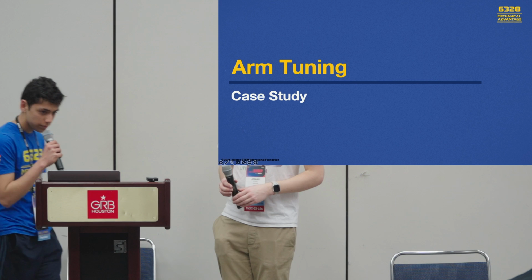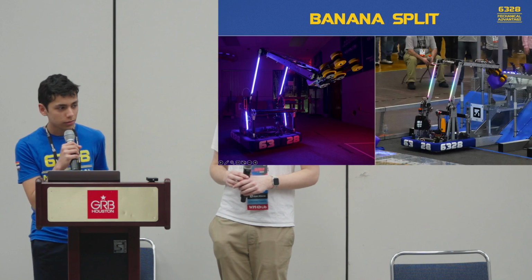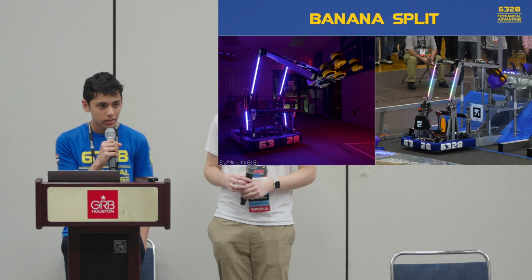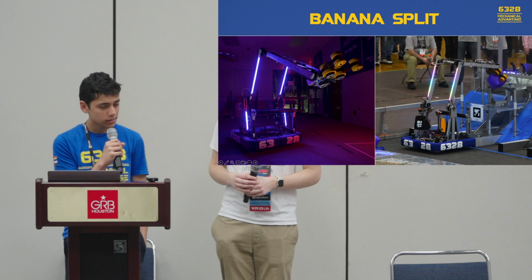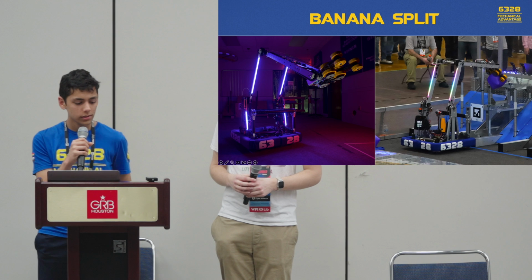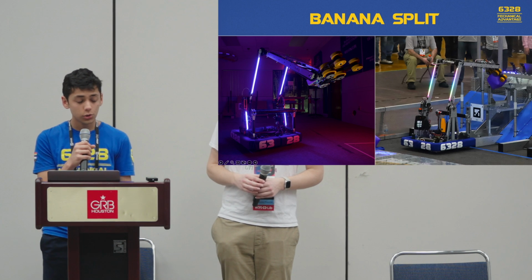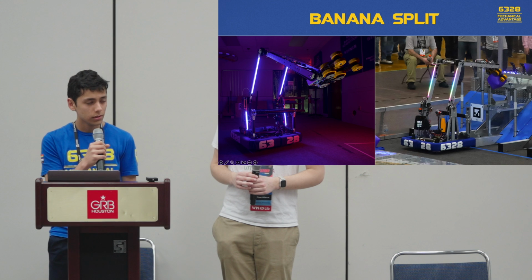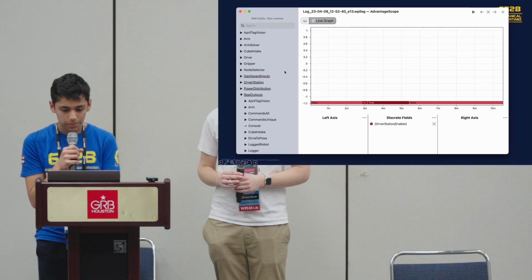So this brings us to our first case study, which is arm tuning. For this case study, we'll be going over our 2023 robot named Banana Split. This is a swerve robot that has a triple jointed arm, which consists of the shoulder, the elbow, and the wrist. For each joint, we have to tune the PID and the feed forward model. So we can go over how we're going to use AdvantageScope to do this.